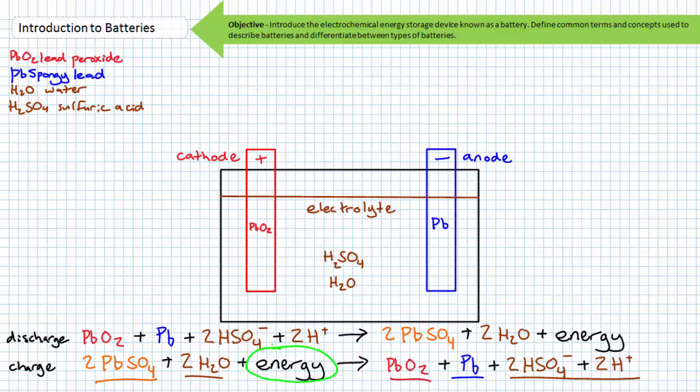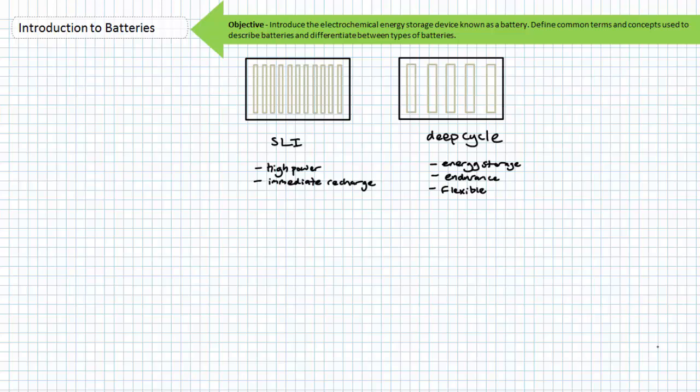By being provided electrical energy from an external source, the battery is compelled to store electrical energy in a chemical imbalance. In a perfect world, a battery would be a limitless vessel for repeated charge and discharge cycles. However, a full discharge causes strain, and each cycle permanently robs the battery of a small amount of capacity. Lead-acid batteries that are regularly deeply discharged and then undergo long periods without a charge experience something known as sulfation, in which the lead sulfate crystals harden and become increasingly difficult to remove during the charge process. As more and more effective area is removed from use, not only is capacity reduced, the chemical reaction proceeds at a reduced pace. This is the principal difference between a starter and a deep cycle battery.